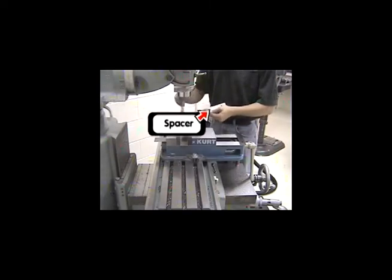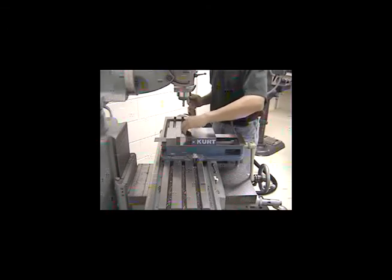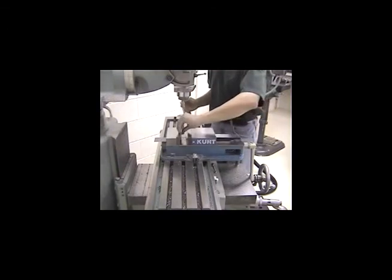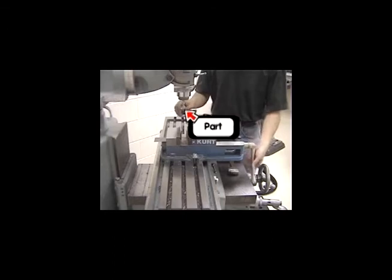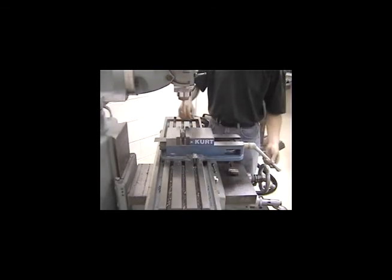Next, clean off any spacers or supports that are necessary. The spacers have two purposes: to raise the part up so that you mill the part and not the vise, and to leave a space below the part so that you drill the part and not the vise. Place the spacers in the approximate position, then place the part and tighten the vise to secure it.